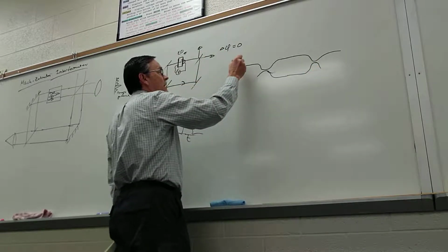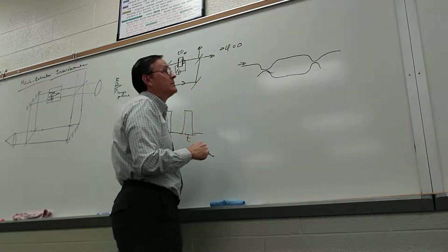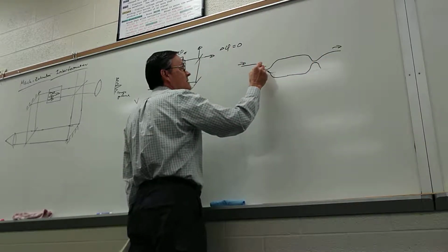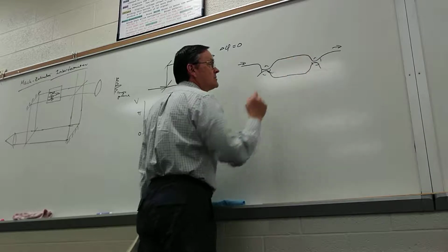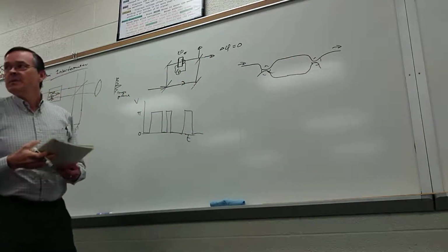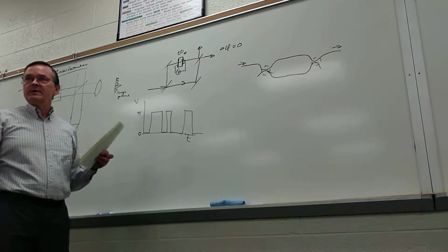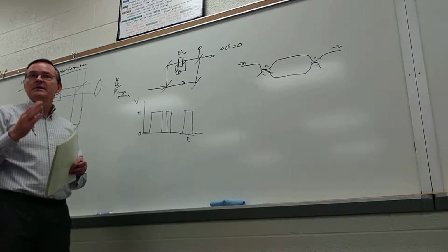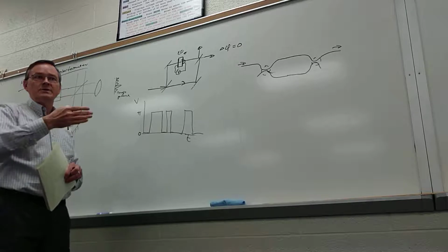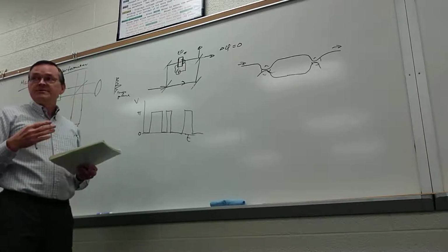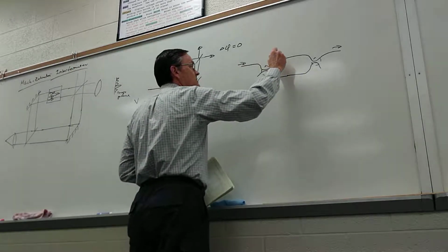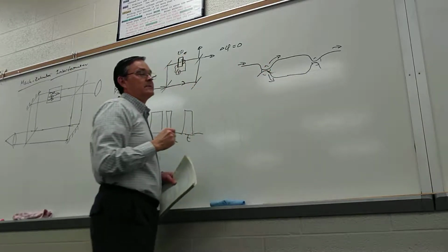And so have your light source be here, and your output be here, and then this and this, those are evanescent couplers. And we talked about how you can take waveguides, bring them close together, and if you have just the right length, then you can get full coupling from one to another. Or in this case, what we want is 50-50 coupling. So half of the incident light here goes this way, half goes that way. Just on top of your reference then.